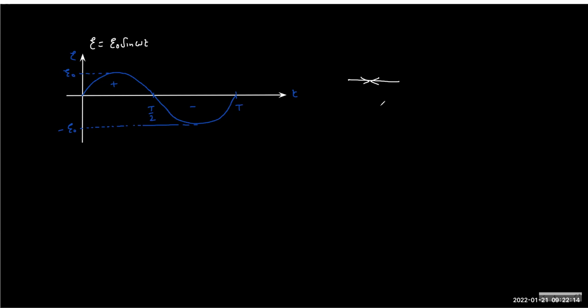Okay. Now the simplest AC generation possible is the sinusoidal. So we have taken sinusoidal for granted for the AC, but AC does not only mean sinusoidal. AC simply means reversal of direction in a circuit. That's it. So I may create a switching circuit in which the current can keep on moving in a different direction, and that I can create using even a DC source as well.